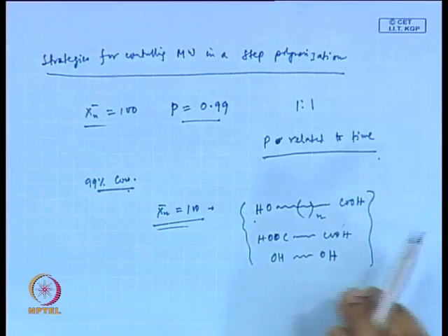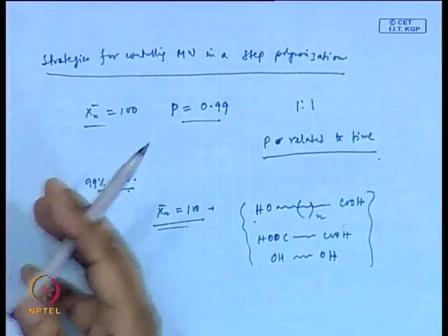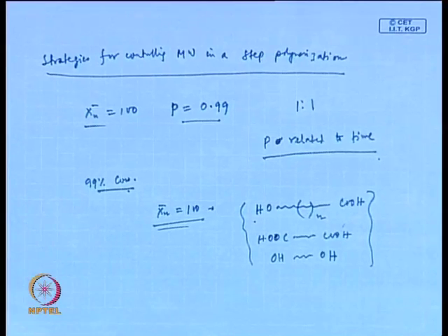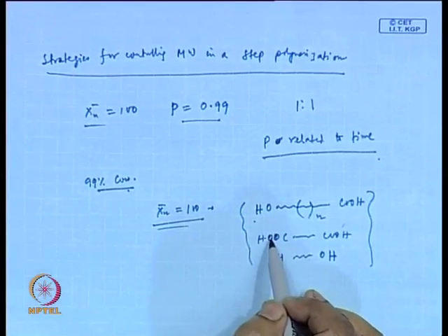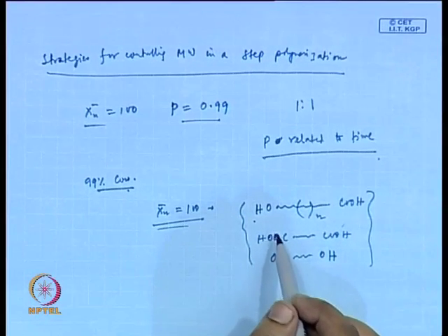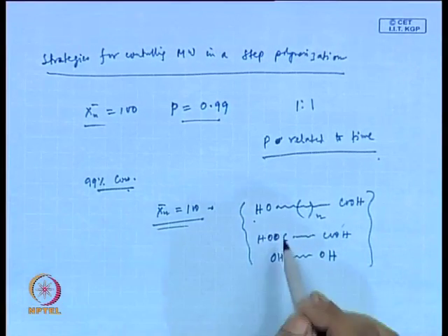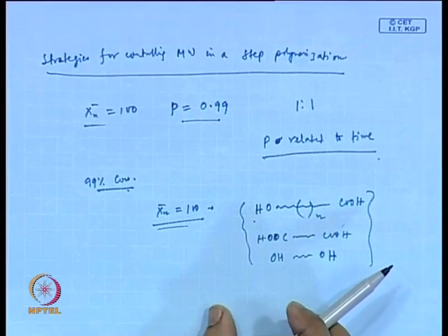So, when you take this polymer at this stage and mix it with other additives and fillers and do compounding, which is a further process done in the melt stage, as I said in the first lecture, then these functional groups are free to react there. They might react and build molecular weight, or they might bite in between and degrade the molecular weight.